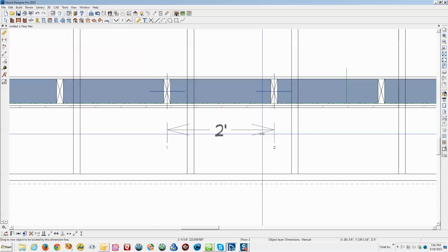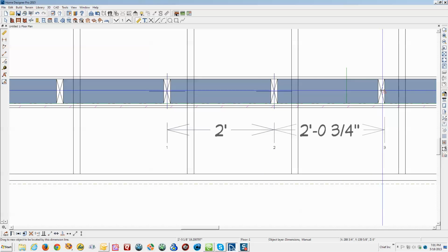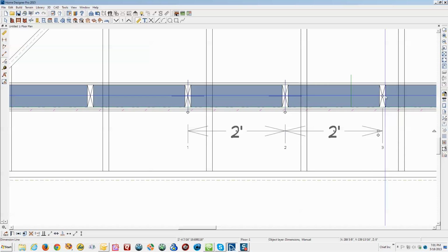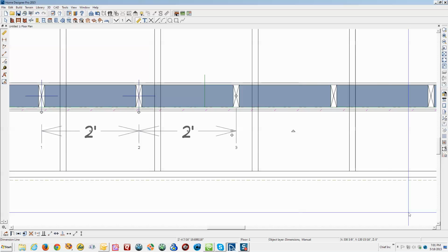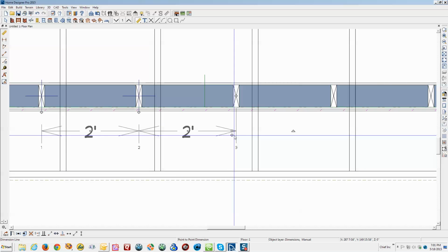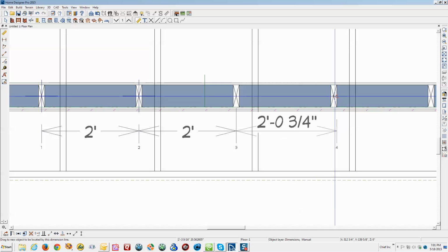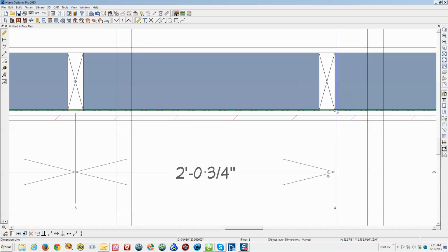And let's grab that additional dimension point tool and drag it to the next one. Now on these wall studs, it's working. The first one I used the point-to-point tool on, but now it's extending. And you see it'll snap to one side or the other or the center.